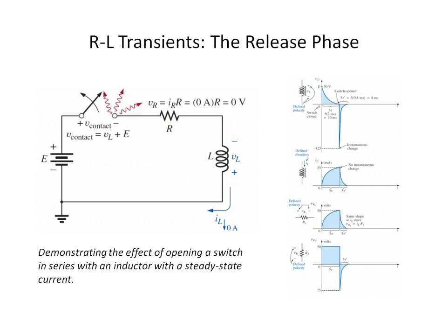Now please note that the way that the inductor was charged, it had a polarity of positive on top, as shown here in this diagram, positive on top and negative on the bottom. When the inductor is discharging, when it's releasing its energy back, please notice that now the positive of the inductor is on the bottom side with the negative on the top side. So in other words, when it's charging and then when it discharges, its polarity will reverse. Now, how does that affect things?